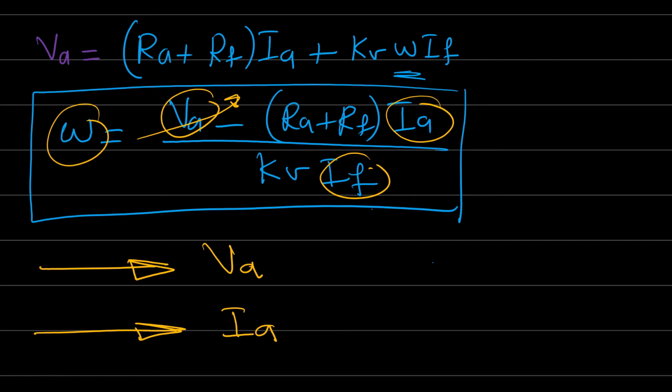Now, let's draw the relation between the torque, power, armature current, and the speed, and see what happens. We said that the armature current is a measure of torque demand. So the torque indicates that a series motor can provide a high torque, particularly at starting. That's why series excited DC motors are commonly used in traction applications.